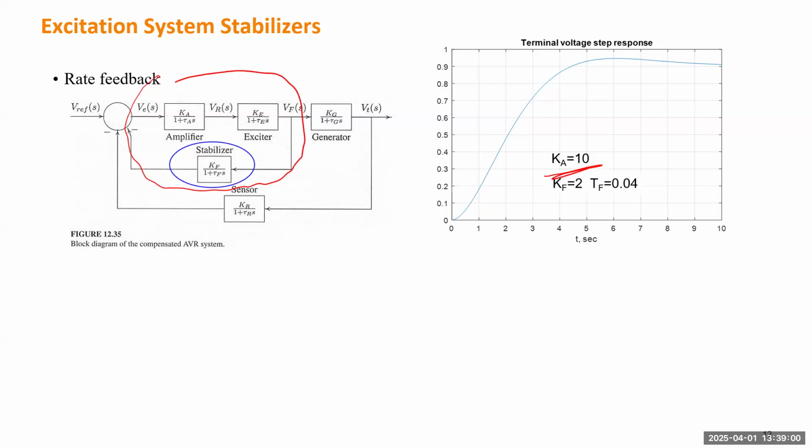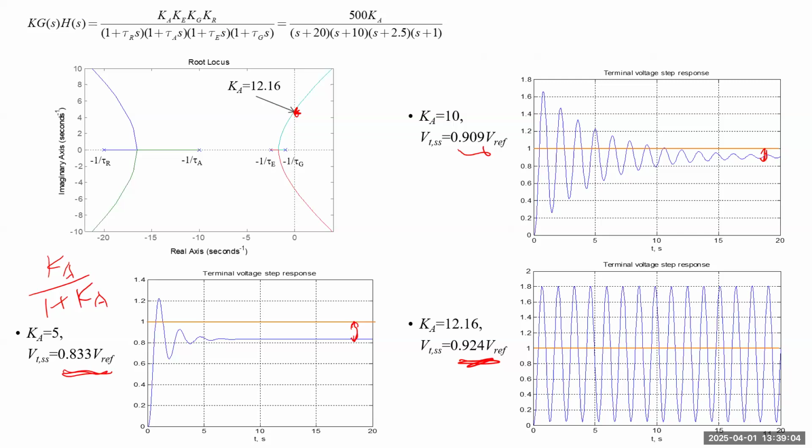Yeah, it should be covered by linear system control. Like for this case, that's the original open loop transfer function, right? So it has 4 time constants. Each time constant determines an open loop pole, which is drawn here.